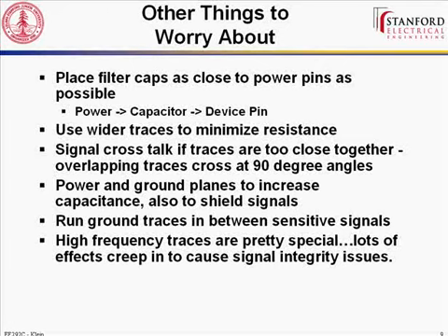Once you finish the layout, will the software be able to check if it's consistent with the schematic? Yes. So the question is, once you finish the layout, will the software be able to check for consistency with the schematic? And it will indeed. And we'll go through that whenever we can. It has to be either Thursday or Tuesday. So you say you give us details of how wide our traces can be? Yes, so I will give you the tolerances basically for the project, which will specify the minimum trace width, the minimum trace separation, the minimum annular ring, the solder mask swell, and some of those parameters.